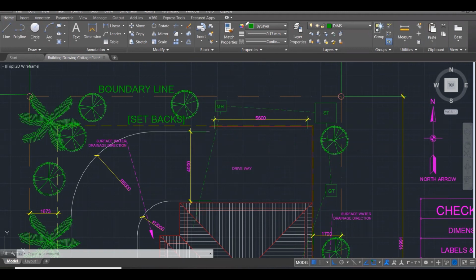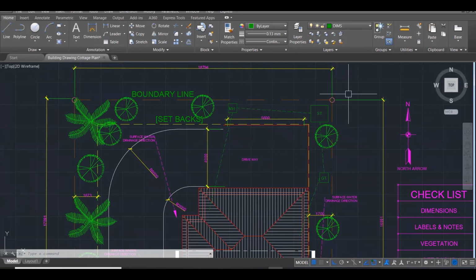You try not to bend pipes. When you bend pipes, that means the waste is stuck at the bent joint, and that can be very difficult to resolve later on. You could get a lot of blockage and stuff like that. So the best thing is to create a chamber, a manhole, creating another outlet on the square so that the waste comes in there and turns the corner in a very natural way rather than trying to force it through a bendy pipe. It makes sense. If you guys know anything about manholes, you can check it out or do further research to see how they work.